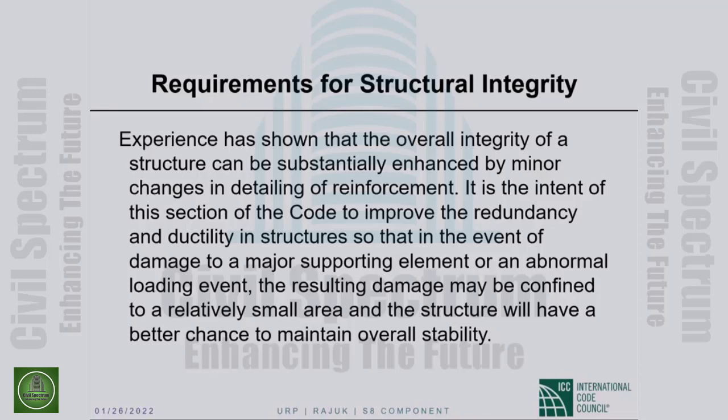So the minimum gap between the upper layer and the lower layer of reinforcement is 1 inch. Okay. So the question is, if I understand this, is there an upper limit on that gap? The answer is there is no upper limit. But if the further away you go from the tension face with these layers, the less effective your reinforcement becomes, right?